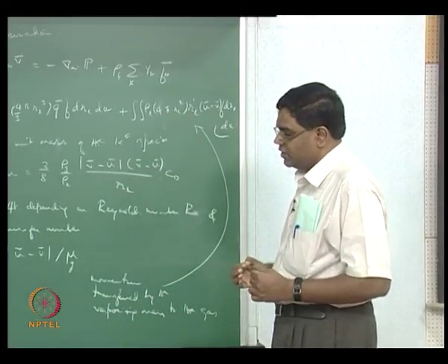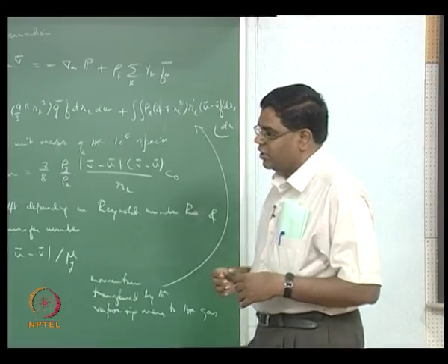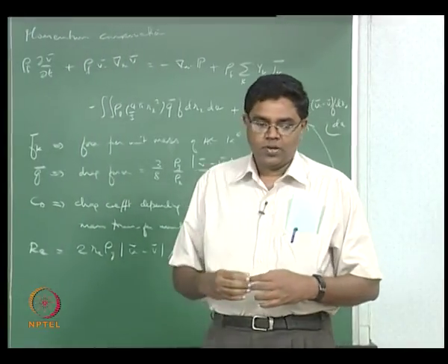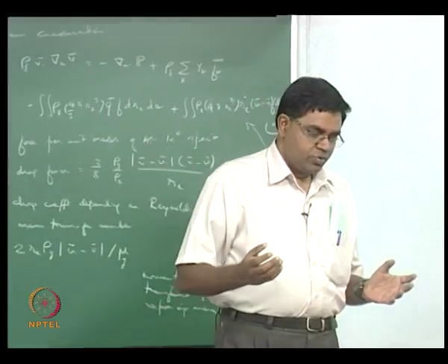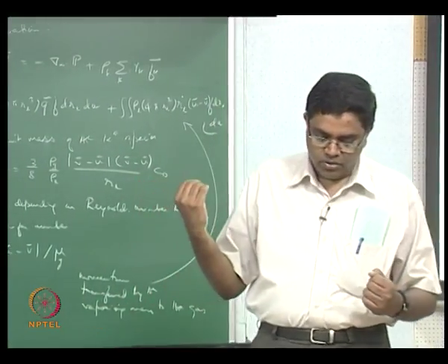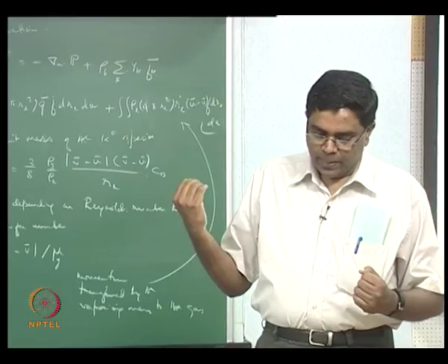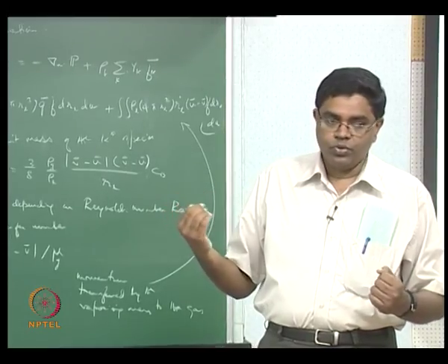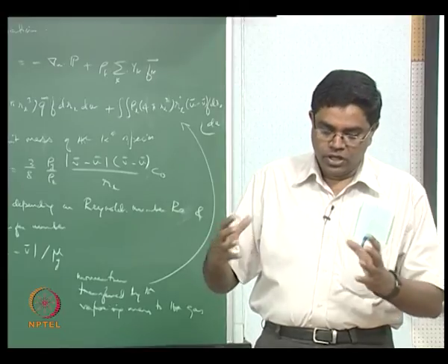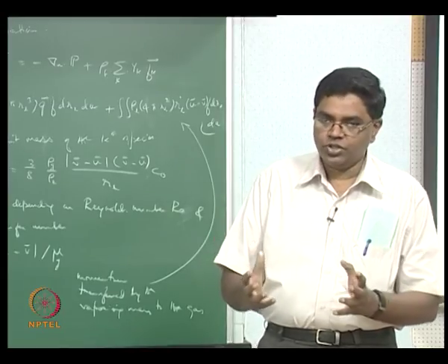This is pretty interesting. The other thing now, if you begin to think about these droplets burning rather than just evaporating, and let us suppose that we were talking about the group combustion number, which allows for individual droplets to have flames associated with them.